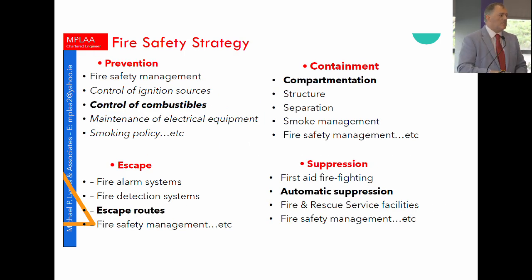Now, whether it's performance-based or prescriptive-based, the strategy is still based around very similar things. It's still a B1 to B5 concept, because there are five legal building regulations. There are issues to do with fire prevention, the combustibility of materials, your escape routes, the number of people in the room, the number of exits, where they're distributed, how wide they are, what they lead to, how far away they are from your storey exit, from your final exits. You must make similar decisions in relation to compartmentation. Are you getting rid of compartmentation? And if you are, what are the appropriate compensating features to it?